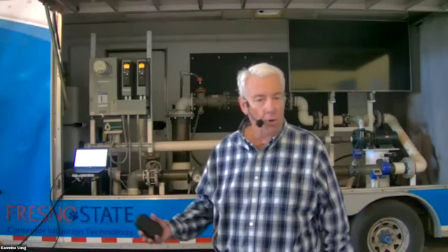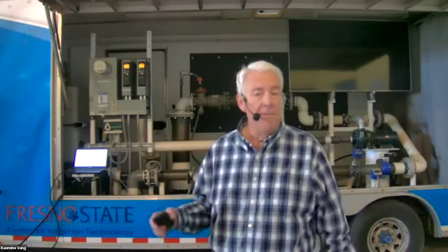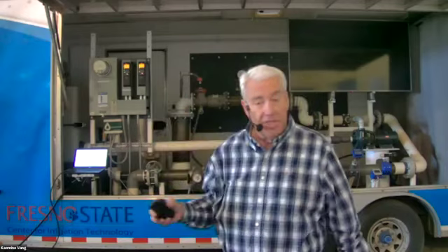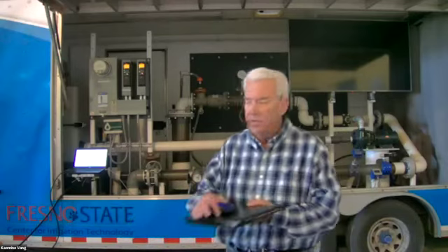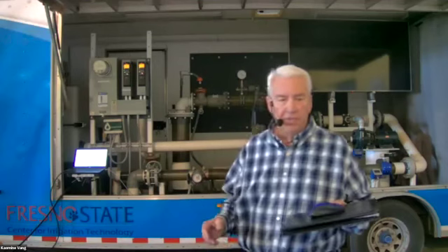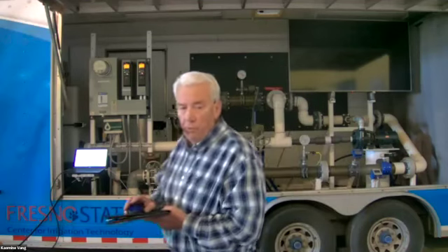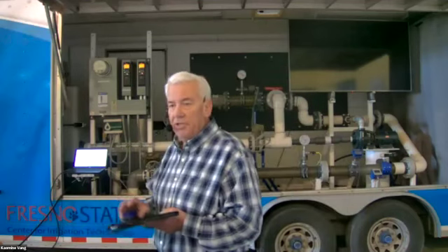No problem, Bill. What's key is understanding what we call the load profile. What different flows and pressures do you need? Or do you need a certain pressure all the time with different flow rates? Because maybe you have different size blocks, or you want to run half of it and not the other half part of the time, because you've got new plants out there, or a different crop, or whatever. You can set up your system to do this, and we're going to set up a load profile on our system now. So let's go to the big screen.